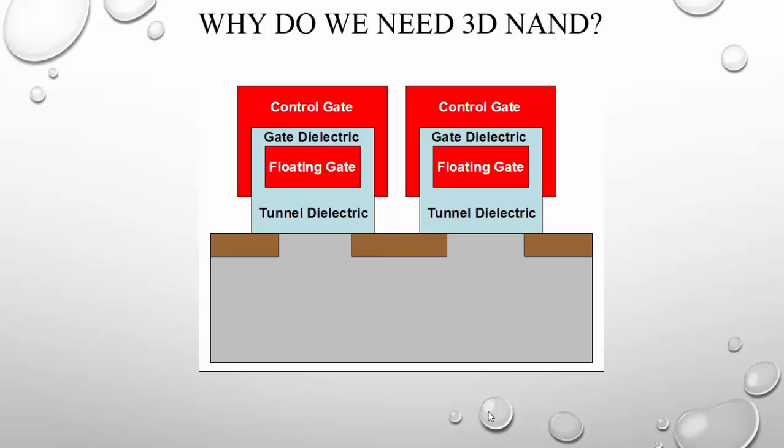Memory chip makers have shrunk the cost of a bit some 9 orders of magnitude since the 1960s, largely by scaling to increasingly tighter process geometries. Flash has always been expected to reach a scaling limit. Over the past few generations, technologists have developed new processes and harnessed innovative materials to push scaling faster than it has gone before. But today we are approaching the point at which planar NAND just cannot be scaled any longer.